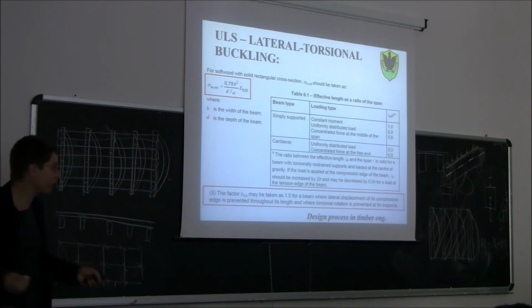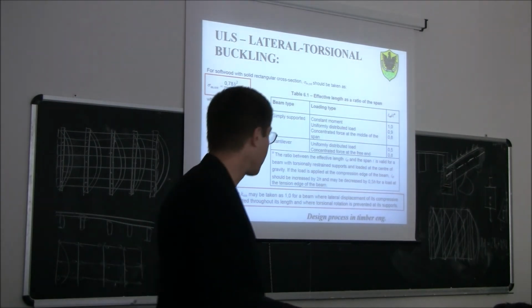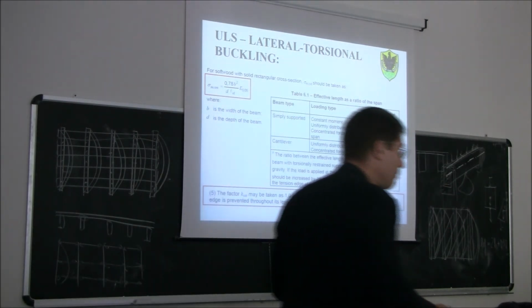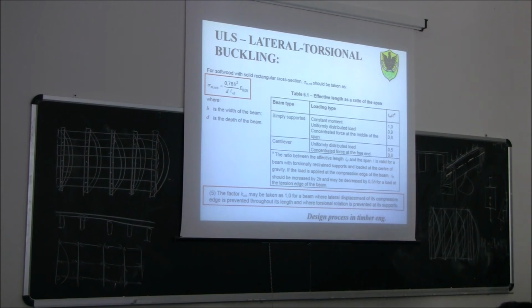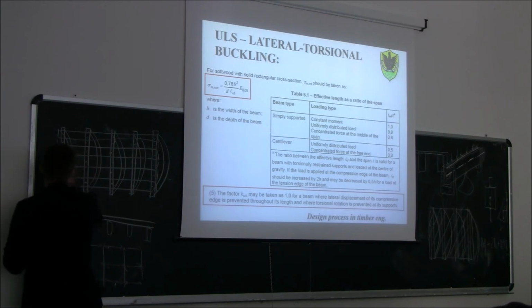In my situation, in order to get to the same situation where no beam can buckle, what should we do here? Glue together the boards. On the top, we could glue or nail another layer of boards to create a kind of grid of boards. So basically, we should widen the board: instead of using narrow boards, use plywood sheathing, where the connection is made by using panels like this.